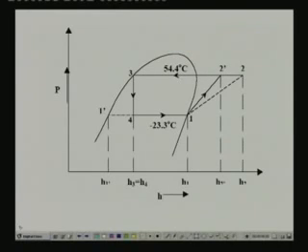Okay. So, this is the information that we have. From this information, how do you find the state properties, various enthalpies, temperatures at various points? So, let us begin with the saturation line, that means point 1 and point 3. This point is already fixed because we know the temperatures, and we also mentioned that this is a saturated condition. So, on the saturated line, specifying any one parameter is enough.